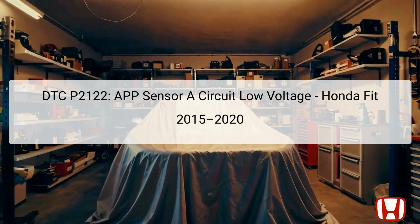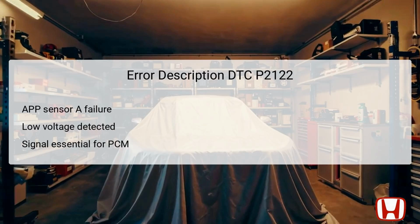Addressing this code includes following specific steps to accurately diagnose and resolve the underlying issues to ensure the vehicle operates safely and efficiently. DTC P2122 refers specifically to a malfunction involving the accelerator pedal position sensor A, also known as throttle position sensor D, where a low voltage condition is detected.